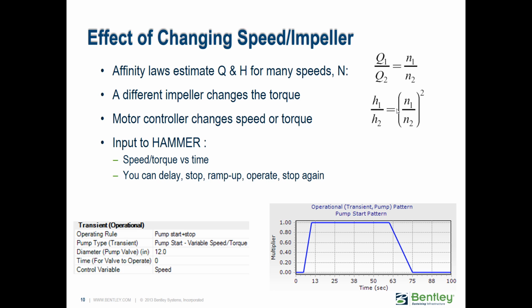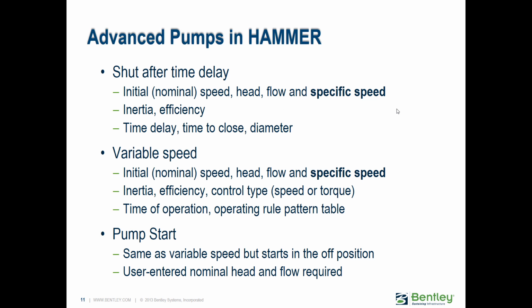So instantly you're applying torque to the pump impeller, and then the rate at which it increases up to full speed or even beyond is up to the inertia. So it's something to keep in mind. It's a very important concept. If you don't realize those assumptions, you could potentially set up your pump event incorrectly.